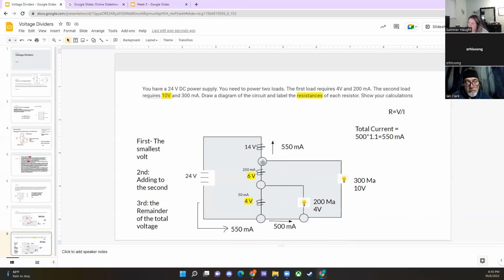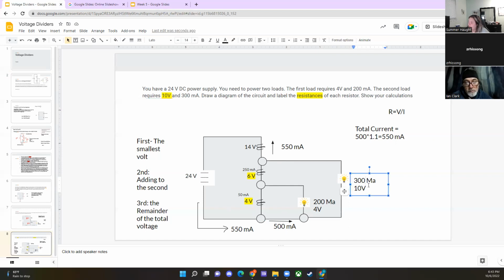So this one is a little bit tricky, and it's because you kind of have to treat all of these circuits as individual circuit components, until we get to the whole circuit solved. So once we determined that this was 250, you can look at it again and see, well, if this is 300 mA coming in here and this is 250, it has to add to 550, right? And that is our check that we did this all correctly, because this added to 550 and this added to 550.